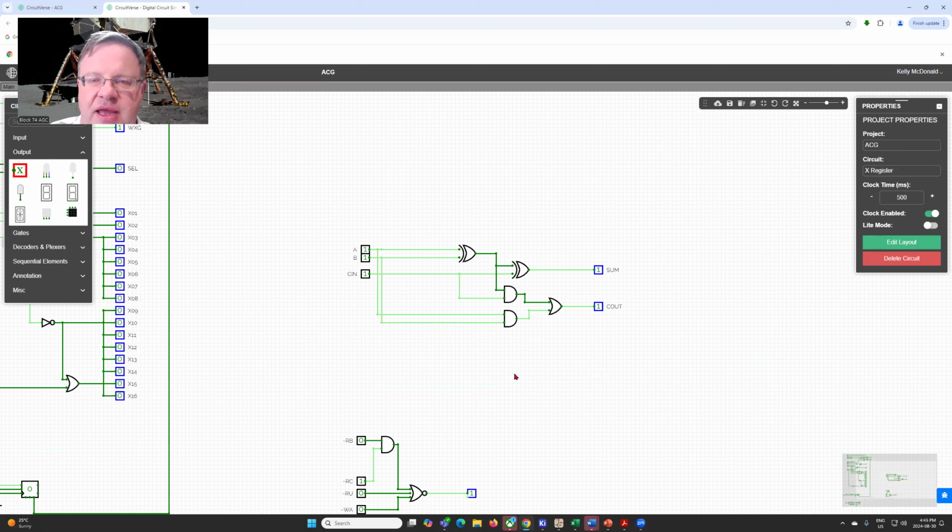So when you build an adder, for every bit you have to have this logic to add the bit. And then you have to tie the carry out of, say, bit 0 into the carry in of bit 1, and the carry out of bit 1 into the carry in of bit 2, and so on and so forth. Now, this comes in kind of two extremes.